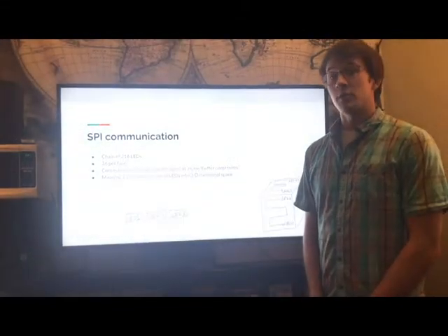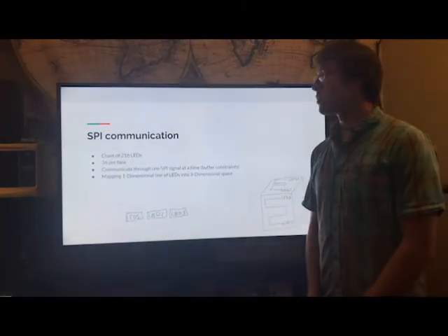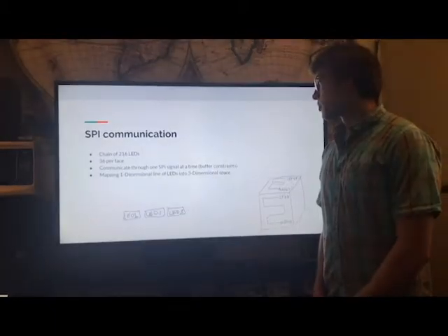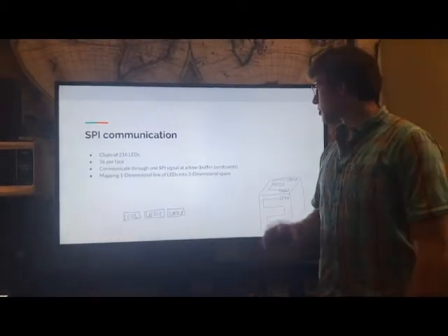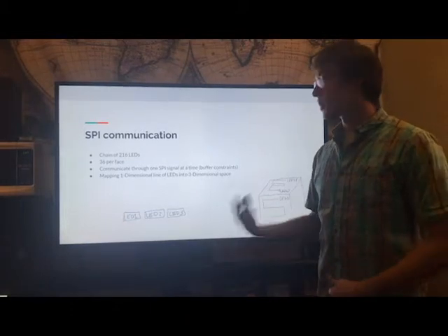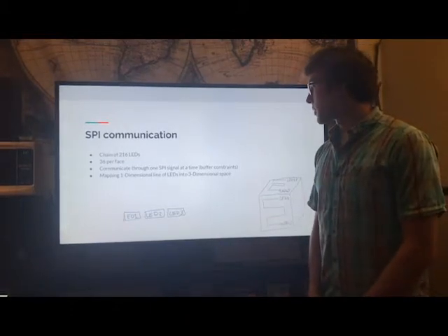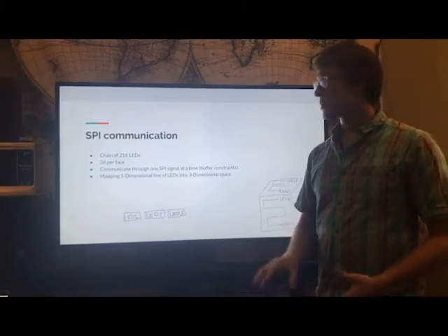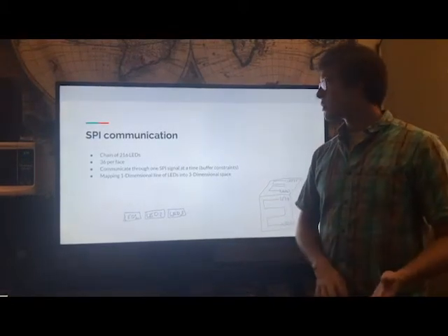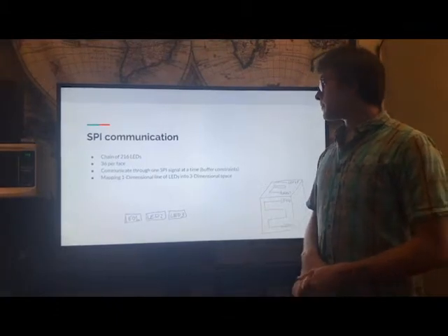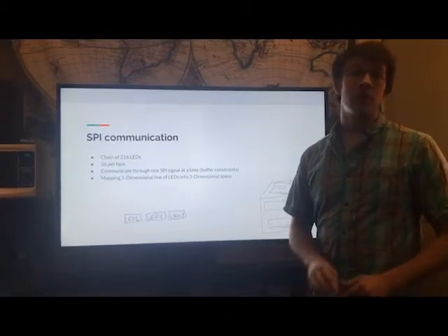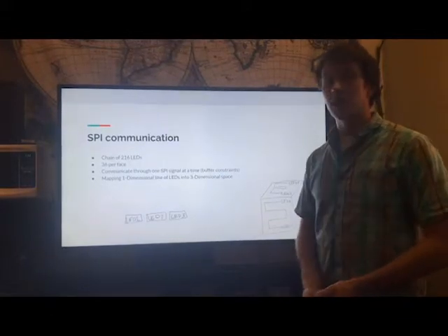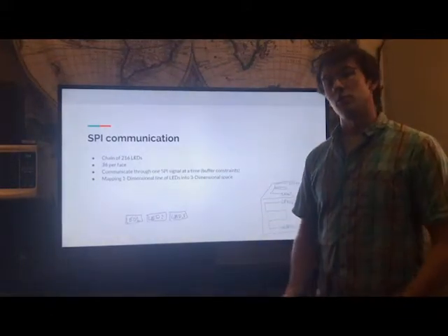SPI communication was really important in this lab because it was how we communicated with the array of 216 LEDs. We did this at various points in our code, from the initial setup when we're selecting bits to throughout the simulation. Every time that we needed to send a signal to the array, you start by sending an initial start sequence of 4 different bytes of zeros. Then you send 4 bytes for every LED, the brightness, and then the specific color that you would like, and then you're sending an end signal that's 4 bytes of just ones.